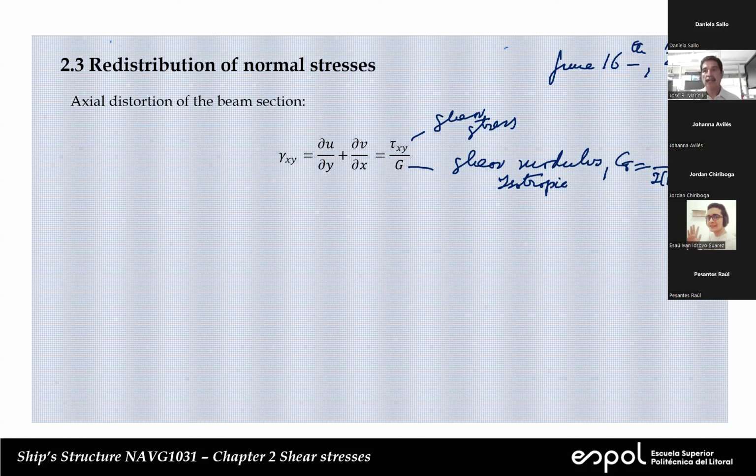Poisson ratio, okay, good. So typical value for the Poisson ratio? Do you remember a typical value for this? 0.3. Yes, it's about that. For steel, it's a good number. In the case of aluminum, which is the other material that we use, it is 0.33 or so, but 0.3 is a good approximation. But if you know the exact value, use it.